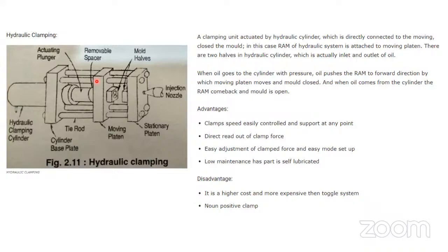This we have to adjust by the limit switch, which is present there, friend. We can easily adjust the movement of the movable platen. Otherwise, if it comes at the same speed, it will damage this, the mold will also get damaged. We don't want the same speed here. Suppose this movable platen is coming at 40 speed, it will damage here. Therefore, we have to reduce the speed. Initially start with 5, 10, like that, and then 40, then again slowly 10 and 5, like that.